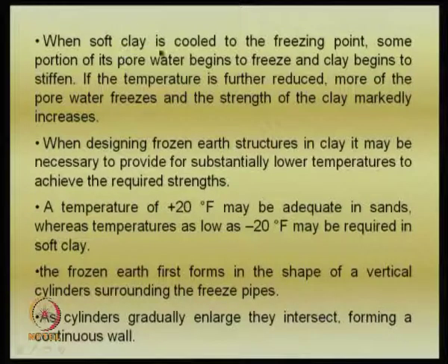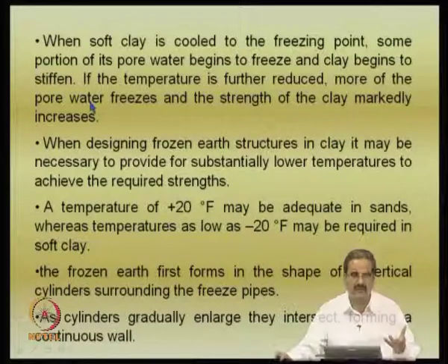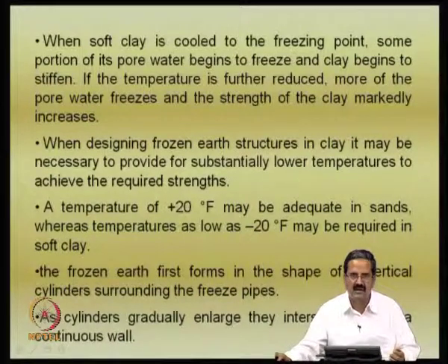When a soft clay is cooled to the freezing point, some portion of its pore water begins to freeze and the clay begins to stiffen. Why it works is that soft soil has a lot of water content, and the pore water freezes and the clay begins to stiffen. If the temperature is further reduced, more of the pore water freezes and the strength of the clay markedly increases. This is actually the mechanism. And when designing frozen earth structures, it may be necessary to provide substantially lower temperatures to achieve the required strength.